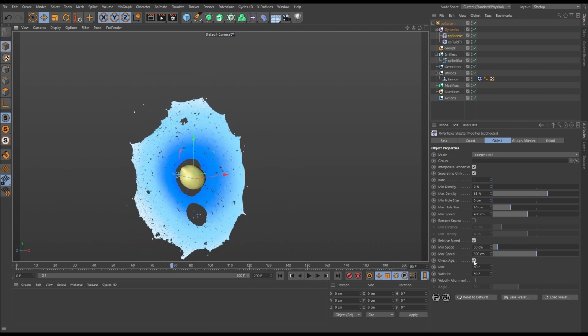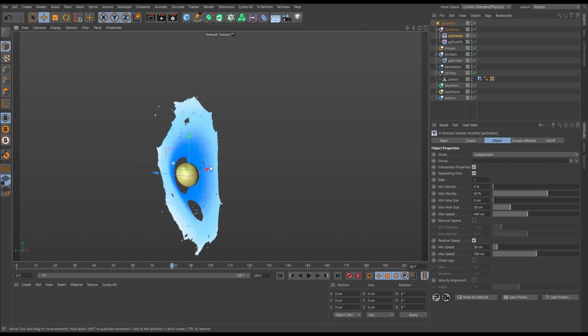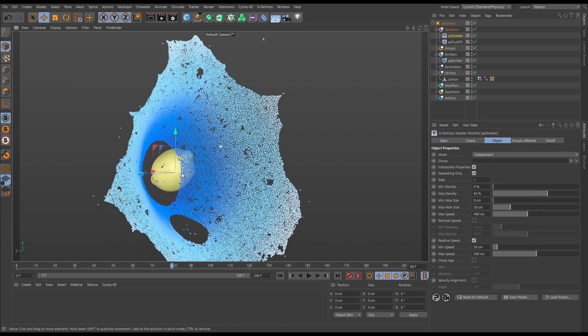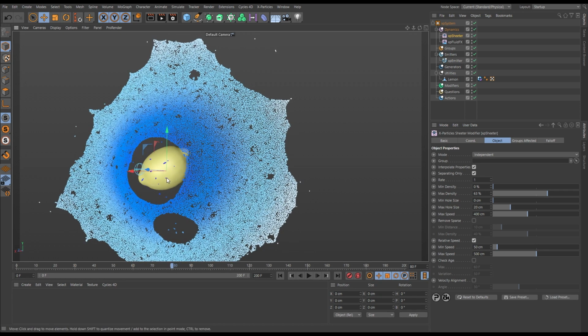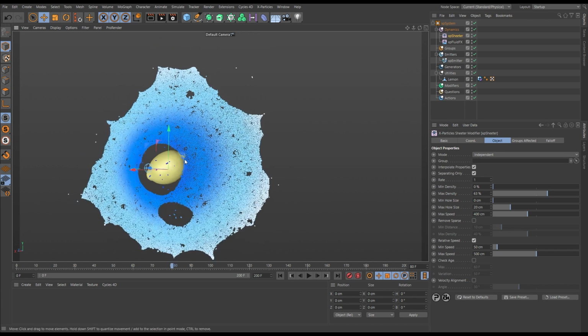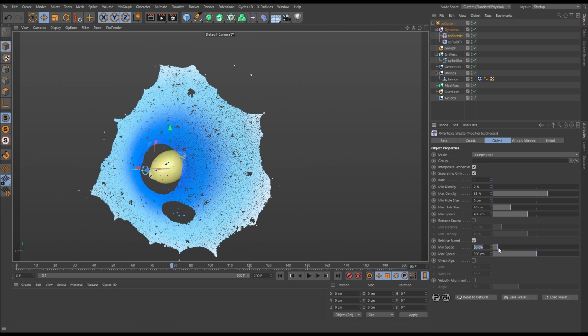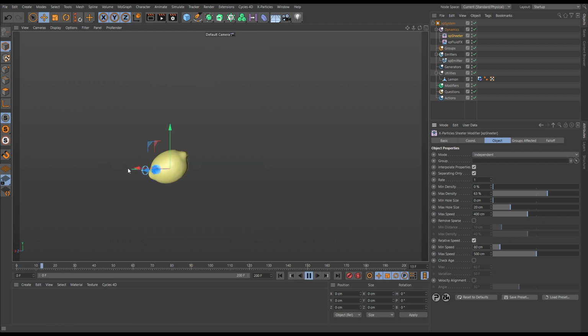Let's switch off that age check. So the minimum maximum speed threshold is a useful tool, especially for stopping slow moving particles from just continuously making a sheet. In this instance, let's just try putting that up even higher. Let's put it up to 80 centimeters. And there we've got this nice hole coming out.